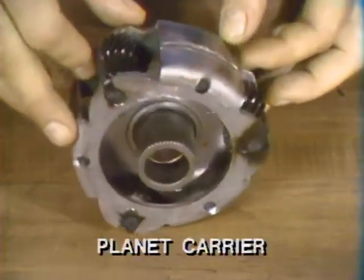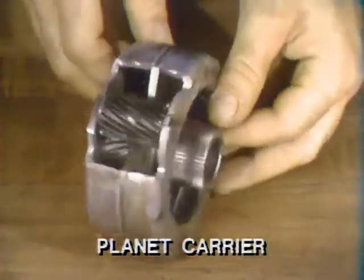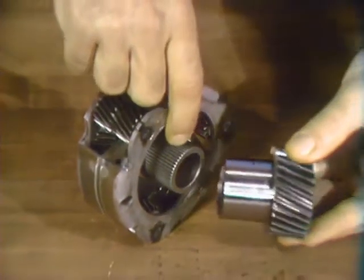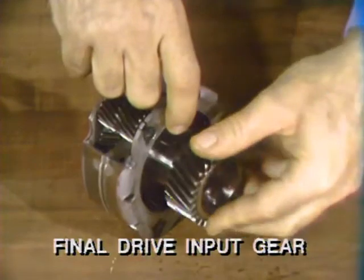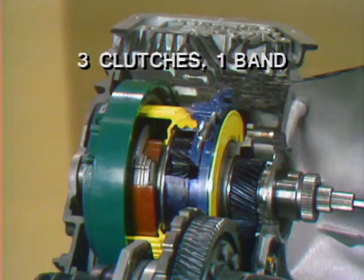The main planetary gear set is a compound design similar to the FMX and the automatic overdrive. But here's the 4th difference. Its output is always through these splines to the final drive input gear. And 5th, the friction clutches and band functions are different because of the gear train arrangement.